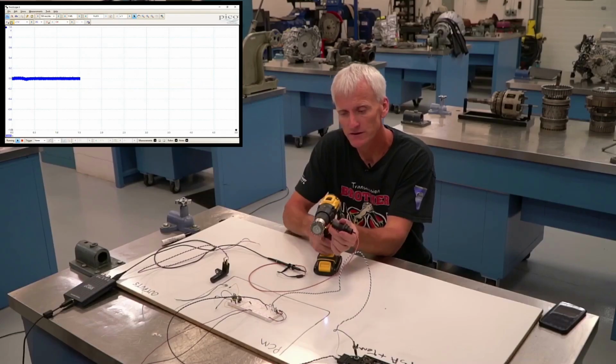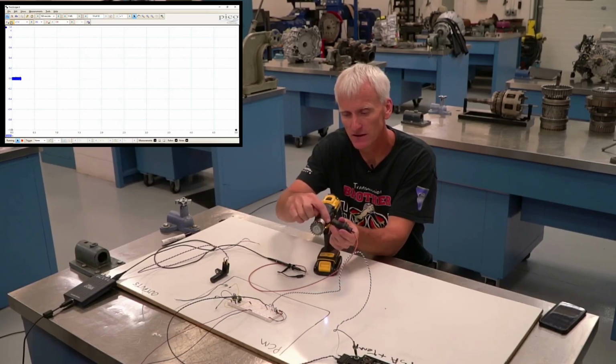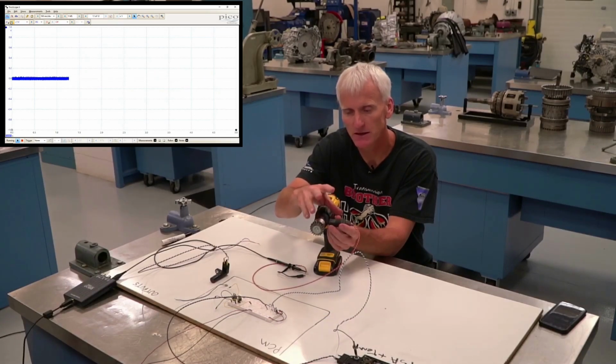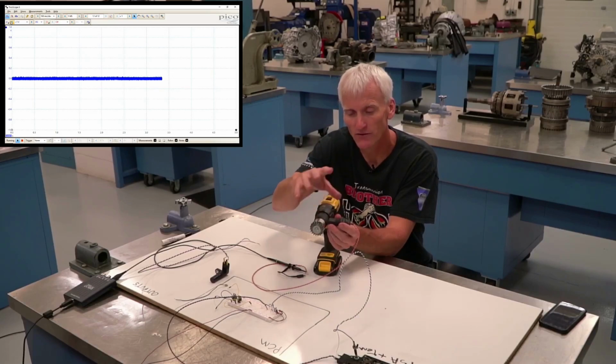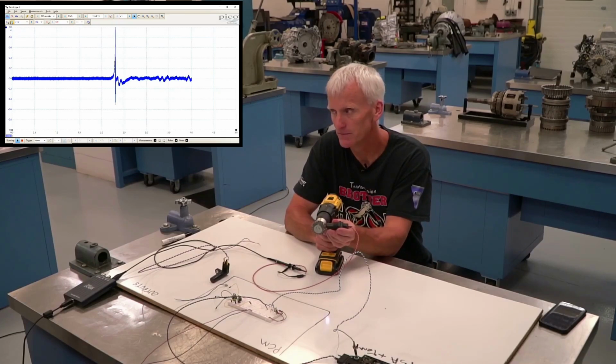This toothed wheel is going to simulate a tone ring. Basically, when these teeth line up against that magnet, it compresses the flux lines in the magnet. Then when the opening is exposed, they expand back out, and when the tooth comes, they collapse. With this constant expansion and collapse, when those flux lines cut across the conductors in here, they induce AC voltage. We can see that on the scope here.